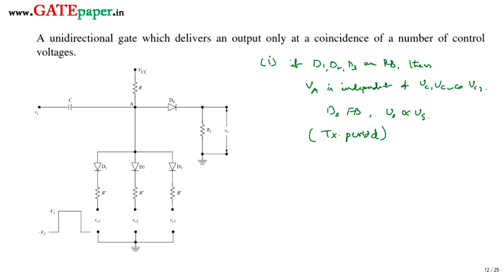Since the diode is forward biased, a current flows, so the total Vcc appears across R itself. Effectively the voltage resulting from Vcc is 0 volts at this point. So whatever signal you apply will be applied directly to the output. Then V0 is equal to Vs, or otherwise V0 is proportional to Vs. Now we'll discuss the second case.